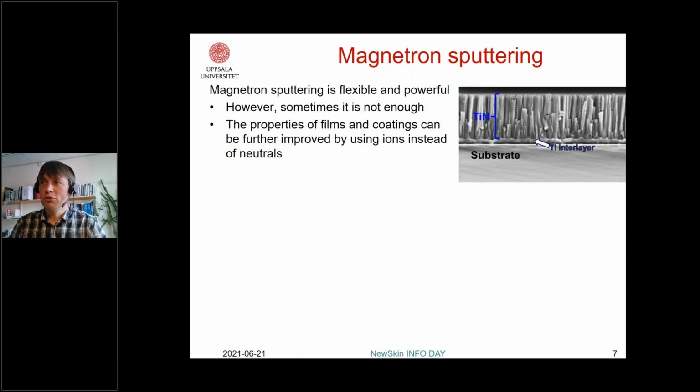But those of you who use sputtering might have seen a typical cross-section. What I'm showing here is a substrate, and here we have the coating or a thin film on the surface. And of course, when we do this, the surfaces look nice and shiny, but if we zoom in and look at how the coating looks in an electron microscope, you would typically see such columns.